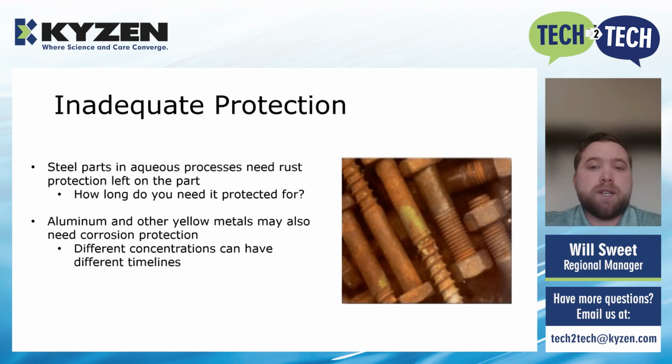If you only need it protected for a couple of days, that opens a lot of things up. In a lot of cases, you don't have to use a dedicated rust preventative product. Just make sure that you have enough concentration and chemistry in the bath so that there is some of the product left back on the part, so you can get that 1 or 2 days.